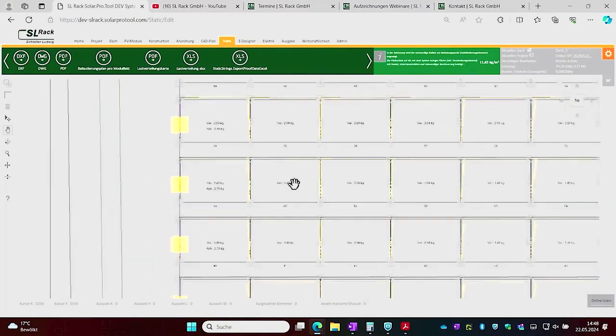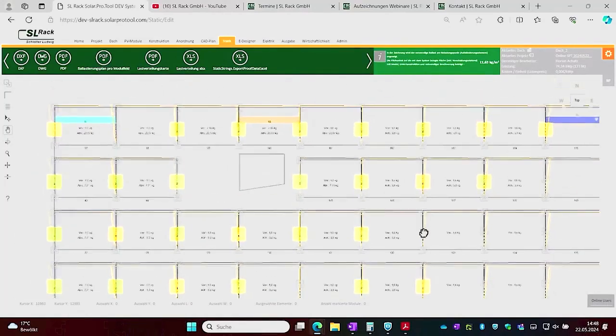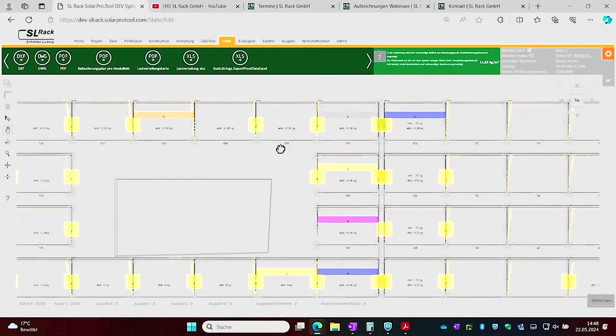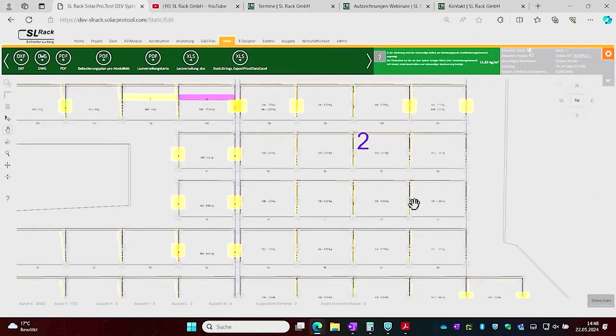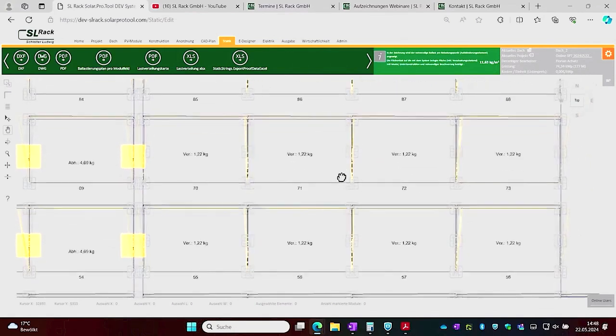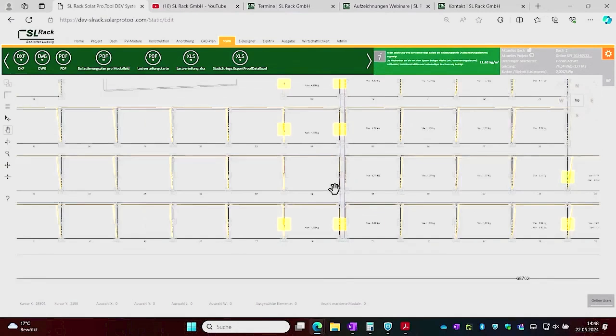With the east-west system, it becomes clearer and easier. I'm right there with you. I'll just quickly go through it. In this particular case, it is designed quite evenly and exhibits a high degree of homogeneity, and that's what I meant. Here you now have the option of ground shoe, base rail, ground shoe, base rail, the intermediate spacer, and then it continues again with the next ground shoe. So here it is designed quite homogeneously.